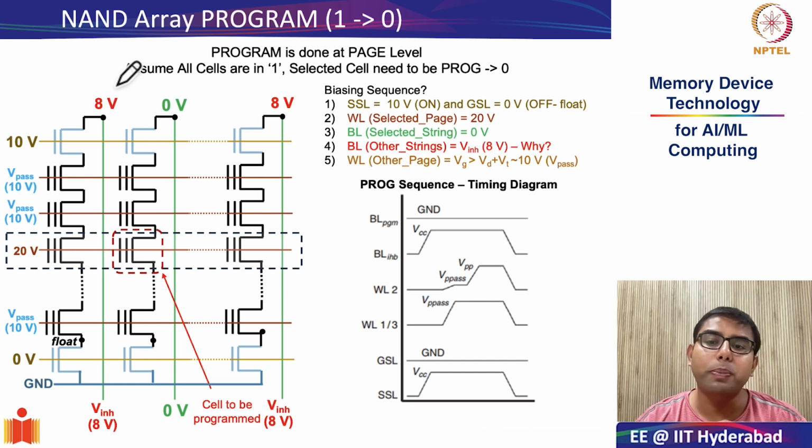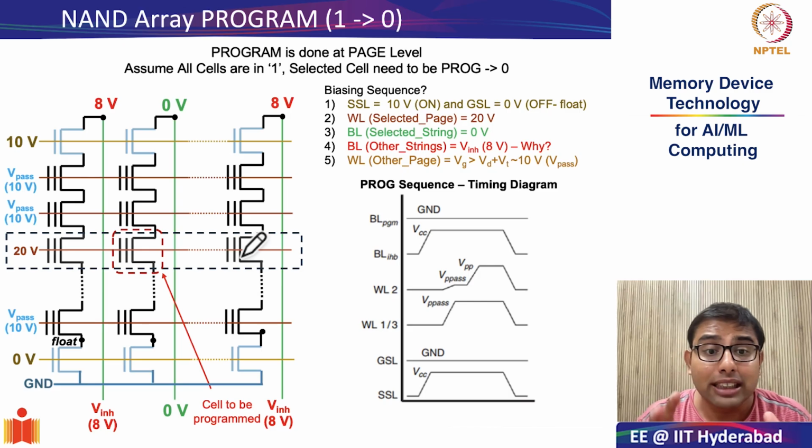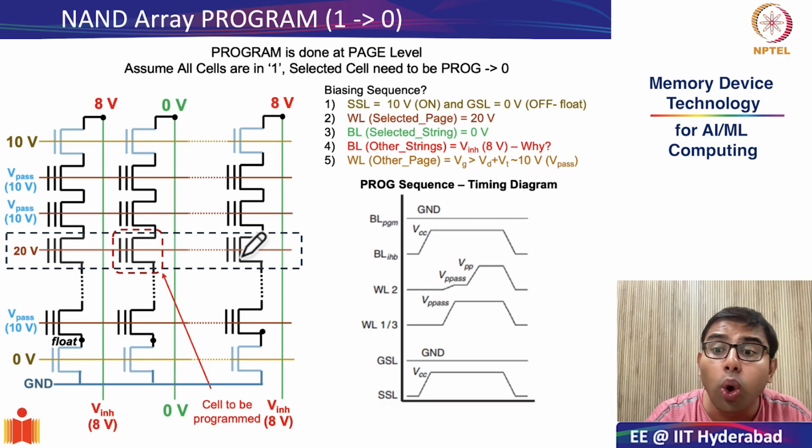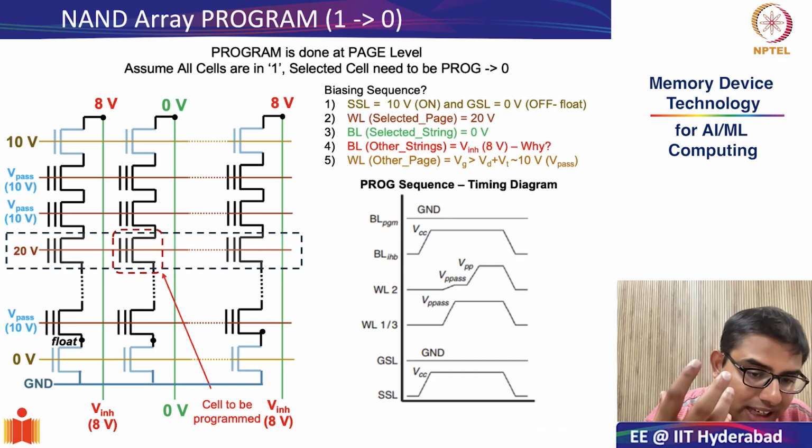One very important aspect I did not really emphasize in the previous class was to appreciate that during the NAND flash operation, especially program operation, it may not look in this particular diagram that a huge amount of data is being programmed, but this is not the case. Please remember, generally in a page, there are close to 64 to 512K bit lines. So at a time, you are programming 64,000 to 512K bits at a time, and this is what makes our NAND flash array architecture very, very special.